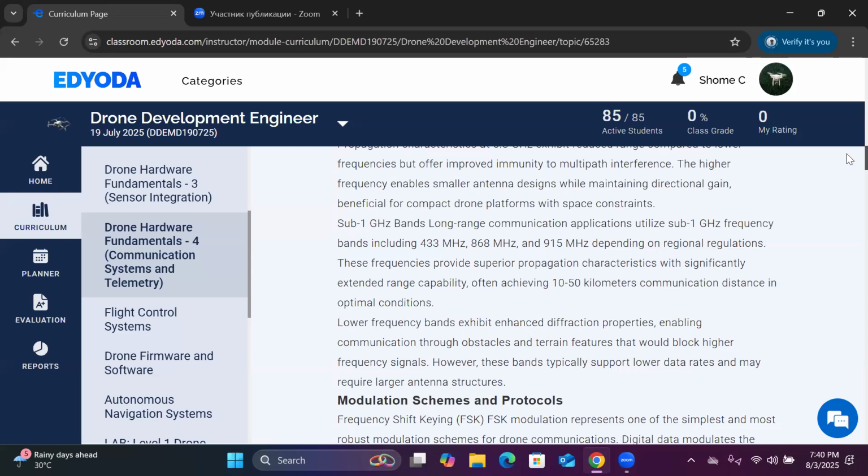So for the UHF frequency band, you will not be able to go with the directional or the omnidirectional antenna. There you need to have a bigger antenna structure like the grid array antenna or the phased array antenna or the larger patch antenna. So all these types of antenna with bigger aperture need to be used for this kind of frequency bands. Okay. So any question so far?